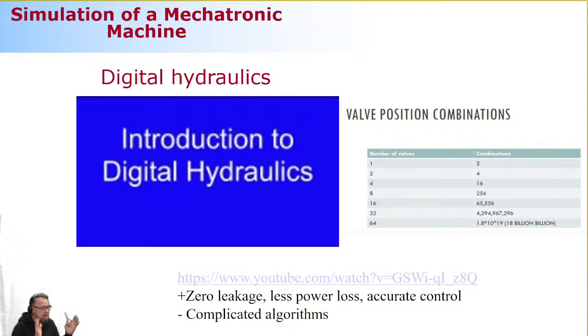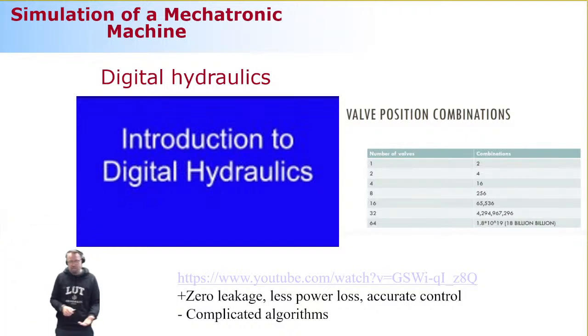And here comes the beauty of digital hydraulics, because you can take digitalization all the way to the pump. A pump which we haven't touched yet is typically a piston pump. When the piston is moving back and forth, you can make a decision in every stroke whether or not you're going to put energy into your system. You can have it move without any pressurizing at all. Or if you have a signal somewhere in your system that I actually need a little bit more energy, then you can act on a need basis. Okay, energy is needed, here is